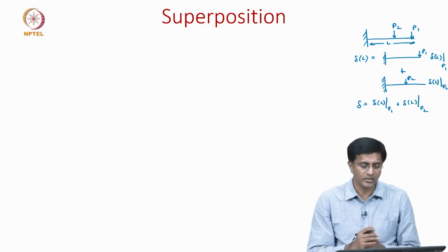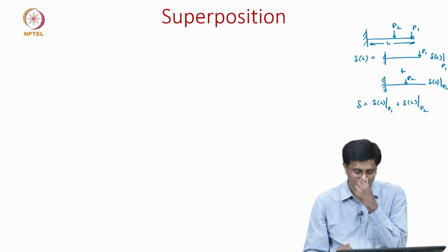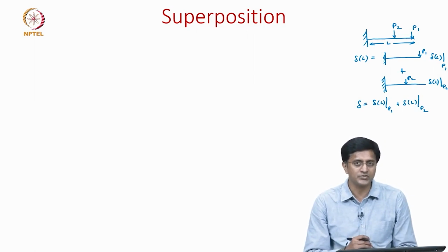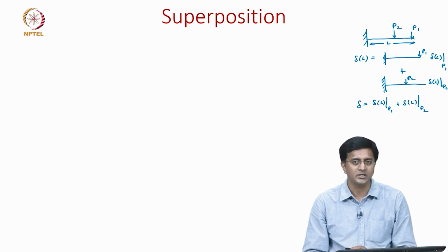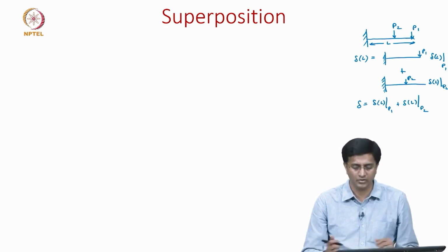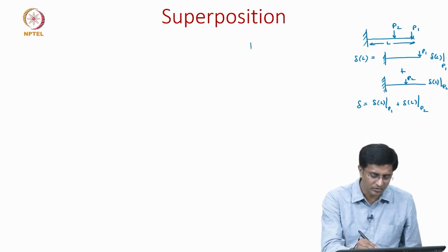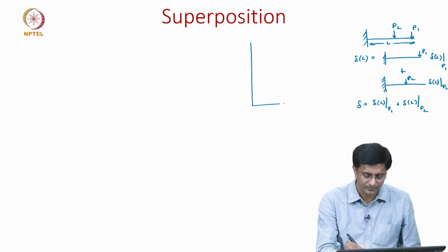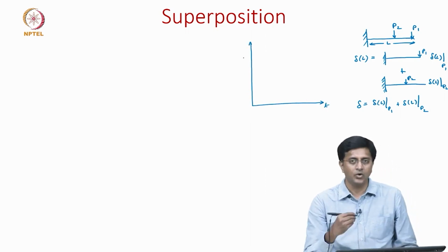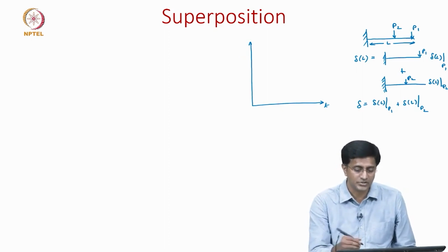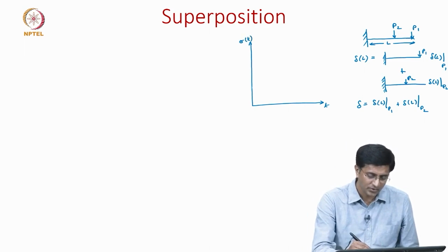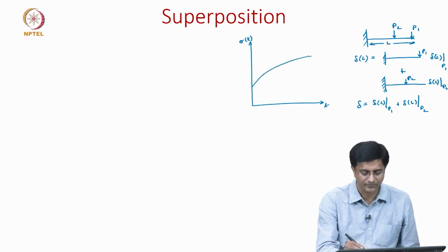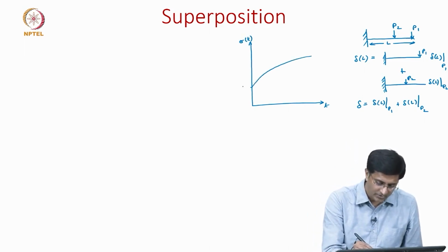The same concepts we can also apply to viscoelastic materials, and the reason why this superposition is very powerful is because it helps you to analyze arbitrary loads or nonlinear loads. So, let us start by looking at a particular load. Let us say with time we have a loading in the form of a stress varying, sigma of t. Let us say it starts with a non-zero value and it is increasing. Let us say the starting value is sigma naught.